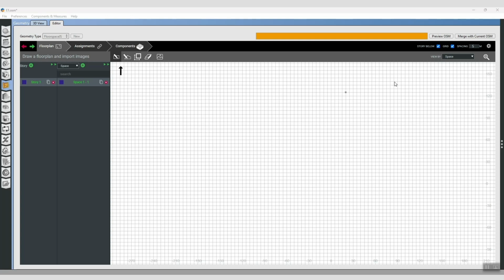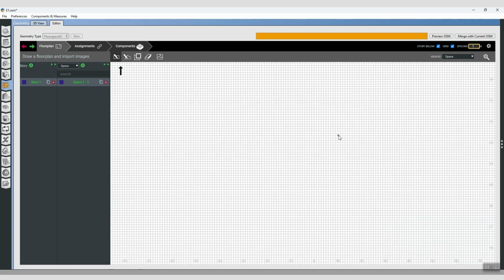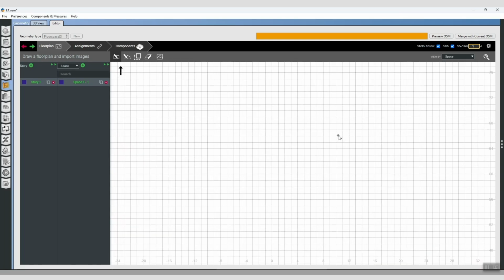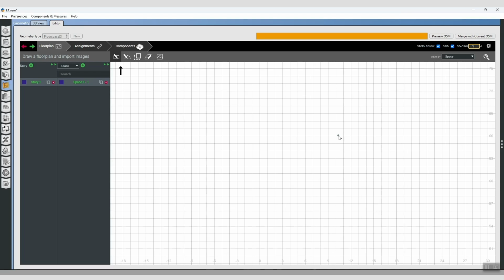Here's what to do. Look at the upper right-hand corner. Make sure the grid checkbox is ticked. When it's on, everything you draw will automatically snap to the grid. Right next to the checkbox, set the grid spacing to 1 meter, just type 1 and hit enter. Now zoom in a bit, roll your mouse wheel or use your trackpad pinch gesture. Perfect. With a 1 meter grid and snapping turned on, every click you make will land exactly where it should. No crooked walls, no tiny gaps.